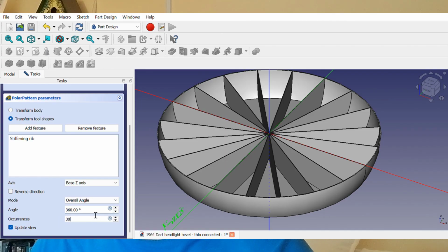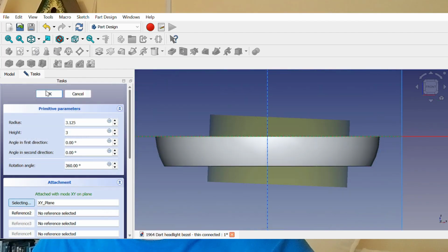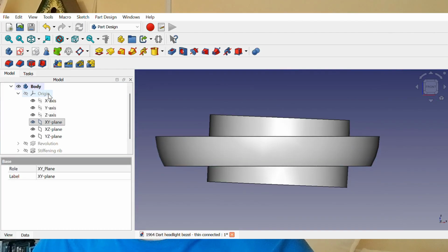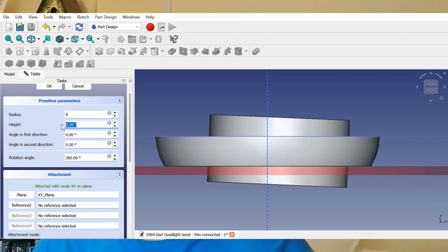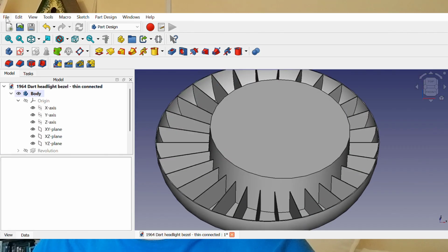Next step is to model the inside portion. Instead of just modeling the first ring, I'm going to use FreeCAD's additive cylinder tool and extend it all the way through the bottom of the outside rim. Then I create a subtractive cylinder to snip off the part extending below the surface. Now I need to create the part where it flares out between the inside and outside portions. There's two steps here. First, a 45-degree flare, followed by a sweep that I'll use the additive loft tool for.